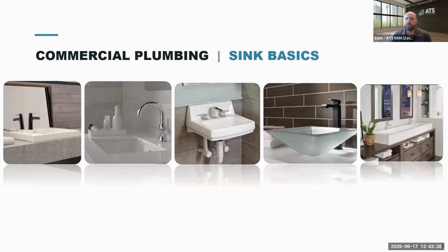Gotcha. We did have some more information come up. They're looking at some of the large volume retail applications, malls, etc. So you're dealing with high traffic, high volume, and generally ultra low flow because most of them are going lead, and you're looking generally at a large trough sink, most likely. Right. So these were applications where the sink's really just not draining well. There's debris left behind.